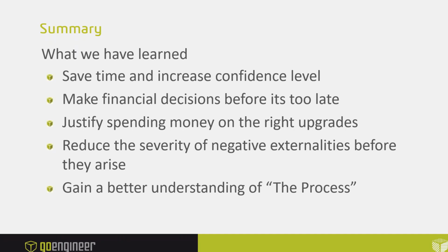With all the examples that we talked about, like all the negatives of injection molding, if we know where there's going to be a weld line, if we know that there's going to be an air pocket, if we know that sink is going to be by X how much, and we know that beforehand, then we can make all these decisions before we get the mold made, so that after the fact we don't have to have an operator stand at the machine, or after the fact we don't have to pay for, you know, jigs and fixtures, right?